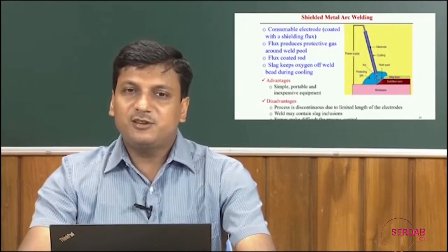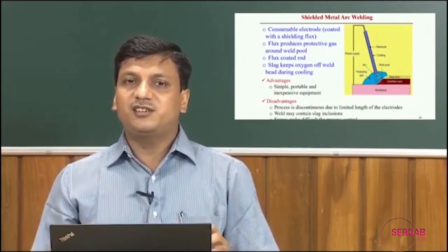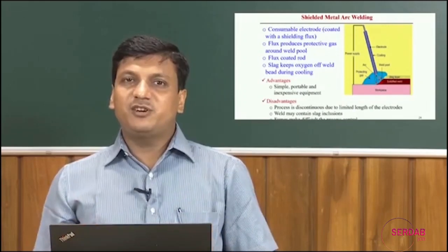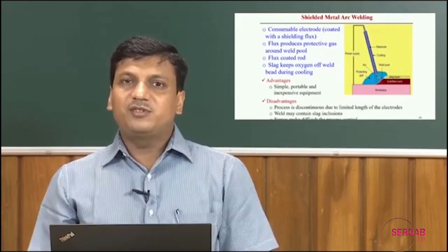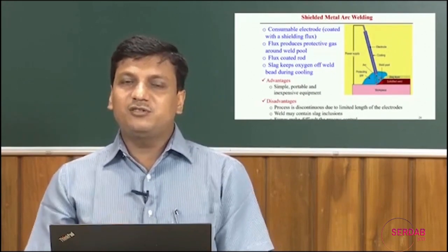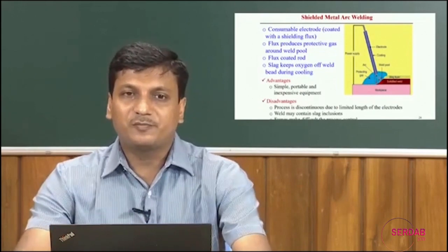So, in that case it is very advantageous to use it in this way. Basically, the electrode is supplying the extra material, and at the same time it is also protecting the weld zone during the welding process, as well as during the solidification process.